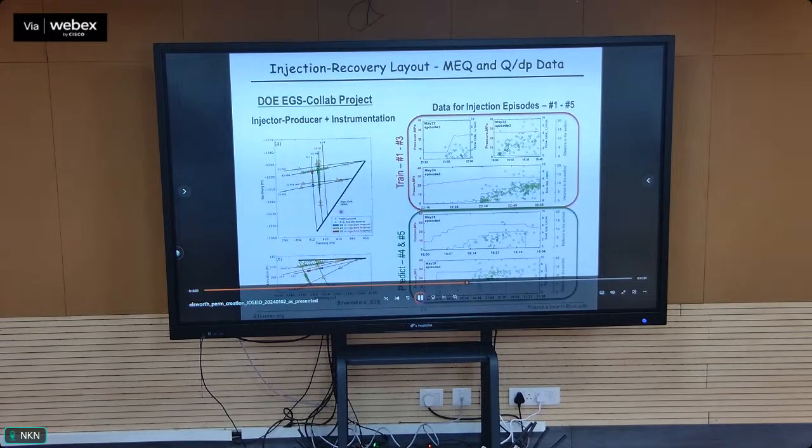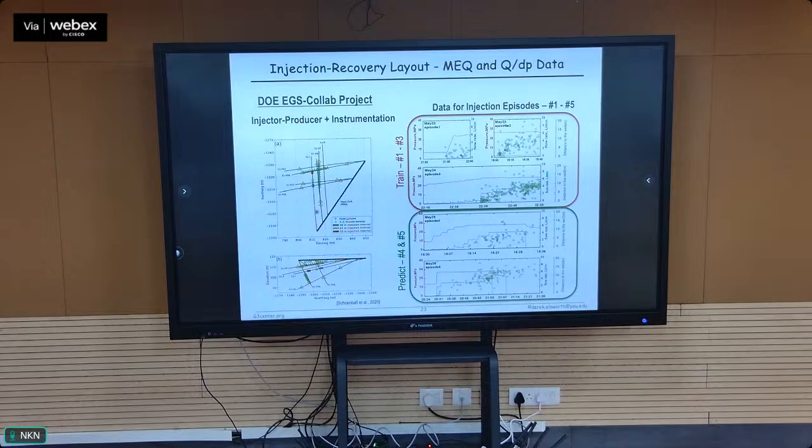So these are perspective views of the adit, the injection borehole, the recovery borehole, and the observation boreholes, which had seismometers and accelerometers set in them. And the injection experiment was run in these 5 different epochs of injection stages, if you like, where the magnitudes of the pressures were stepped up during the experiment. The magnitudes of the injection rate that resulted from those pressures was also measured to correspond to those.